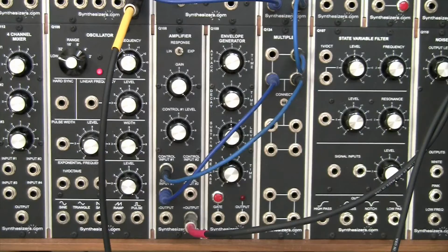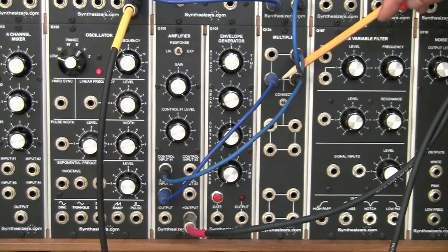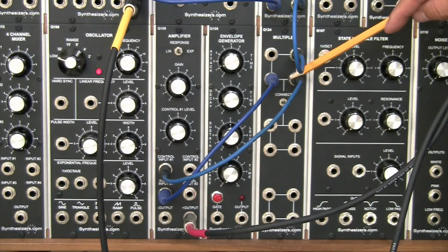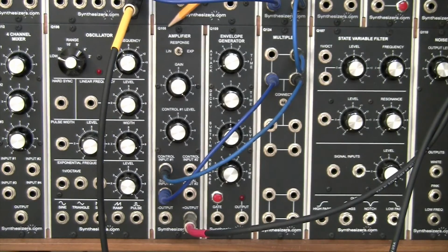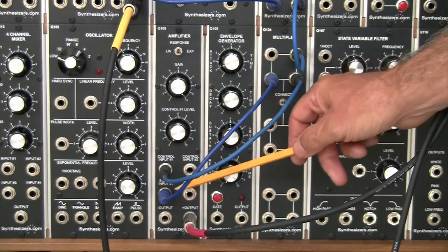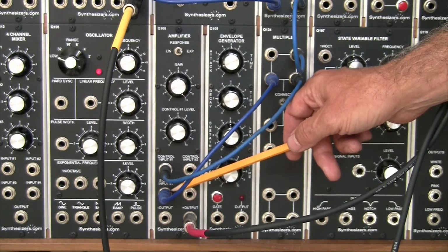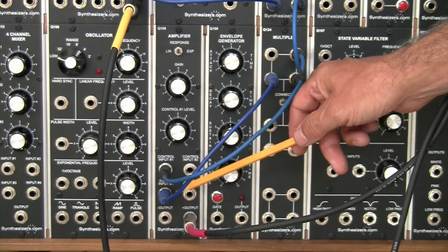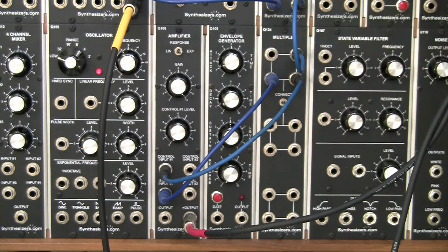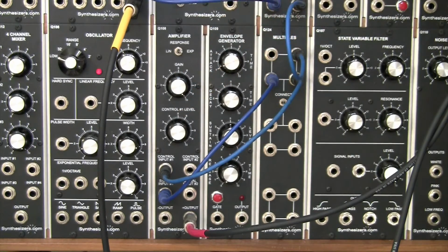The Q124 here, which got its input from the Q109, has two connections, two outputs going to the Q108 amplifier here. And they go to the control input number 1 here and also to the signal input number 1 there. And what you want to do is set the Q108 gain to 10, the control number 1 level to 0, and this mode switch to exponential.